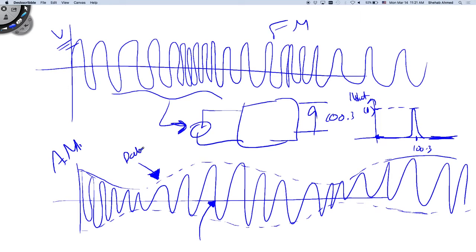And the carrier, or the transmission system, is transmitting at this higher frequency. This is called the carrier in this case. So the carrier signal is this high frequency, and your data signal is this overriding signal that you have on there. Here I have some low frequency overriding signal, and I have a very high frequency carrier.